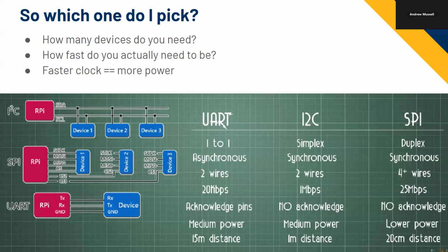In that case, when it says lower power in the SPI column, is that for each individual clock connected to each device, but the line is shorter than chip select, or... Yeah, I think they're trying to say that SPI is lower power because, as we'll see on the open drain versus push-pull, I2C will charge up its capacitance through a resistor. So some power is getting burned by that resistor, and SPI will just short its line to power or ground. So there's much lower resistance, so you won't be burning any power across that resistor. I think they might be trying to refer to that.